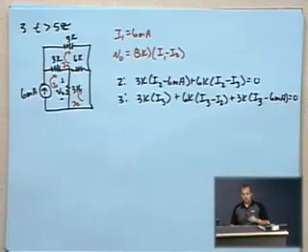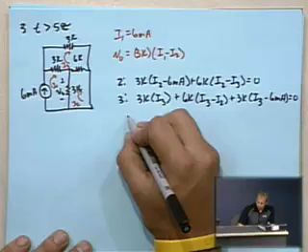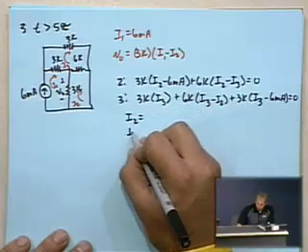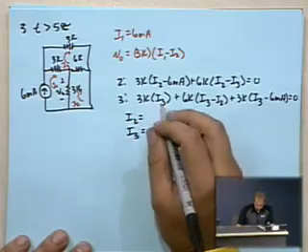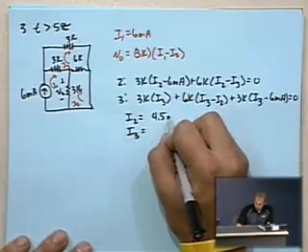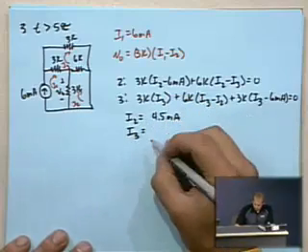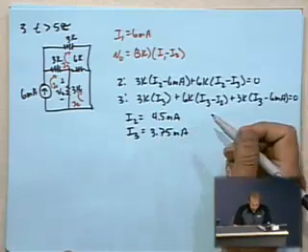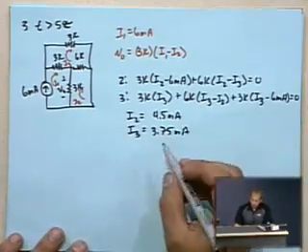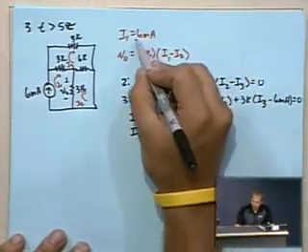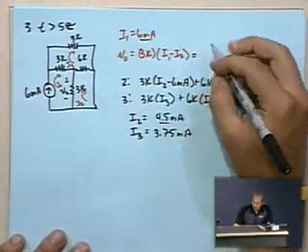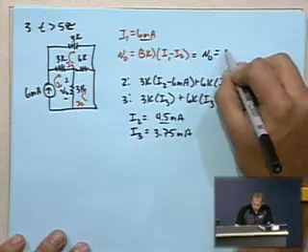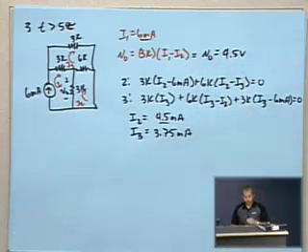Those are your two mesh equations. You solve for the currents I2 and I3, and they respectively equal 4.5 milliamps and 3 3/4 milliamps. We plug that in here, and you get that V0 equals 4.5 volts.